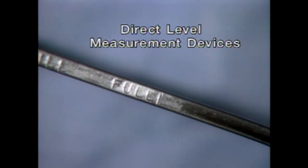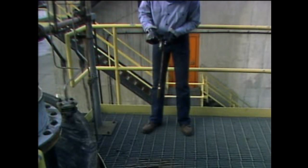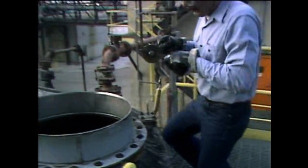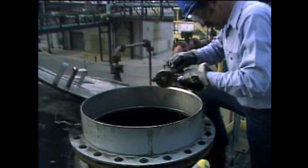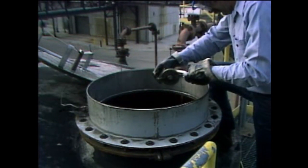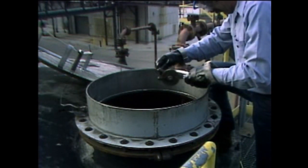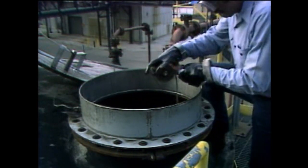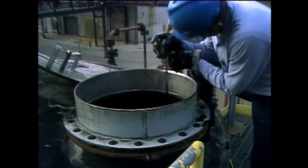Some level measurement devices measure the actual level of a substance directly. These types of devices are called direct level measurement devices, and there are many types of them used in industry. One example of a direct level measurement device is a plumb bob. A plumb bob has a weight that's attached to the end of a reel of flexible measuring tape. To measure the level of liquid in a container, the weight is lowered into the container until it touches the bottom. The tape is then reeled back in, and the level is read directly at the wet line on the tape.